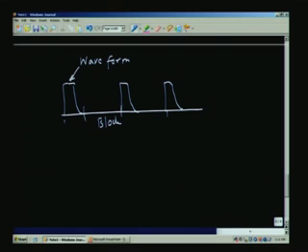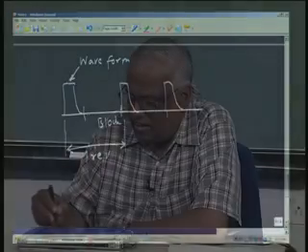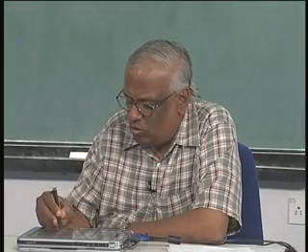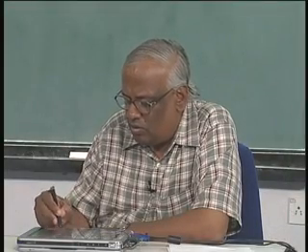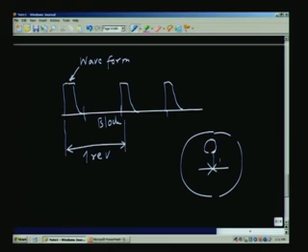So, you see that the period of this, if there is only one hole, will be one revolution. If there is only one hole at 360 degrees, that is, you have an arrangement like this, with only one hole, then whenever it comes in between the photodiode and the LED, it will give you a signal. Suppose I have two of them. So, this is 1 and 2. This will correspond to 1, this will correspond to 2, this will correspond to half revolution.